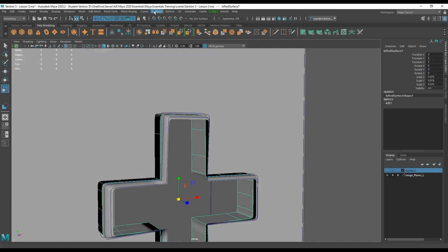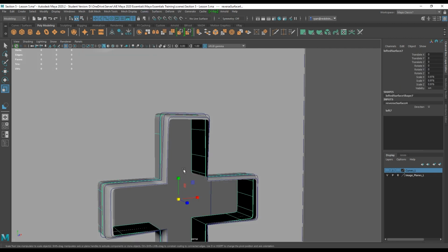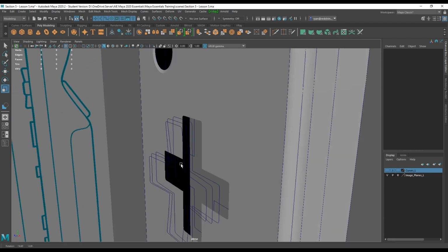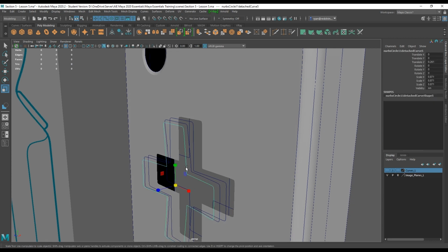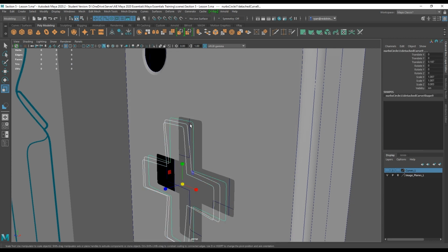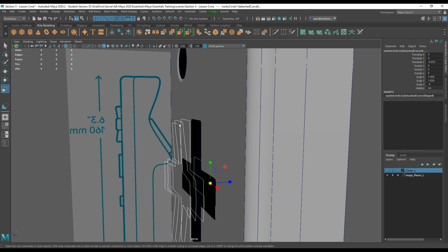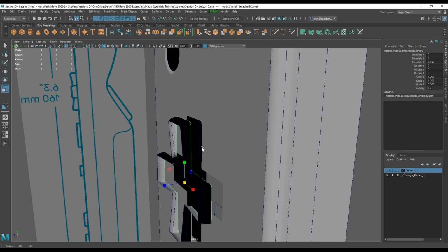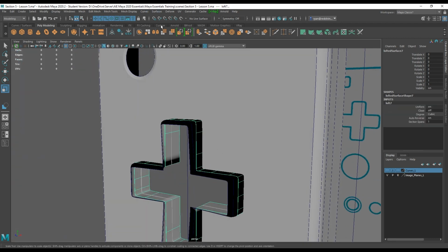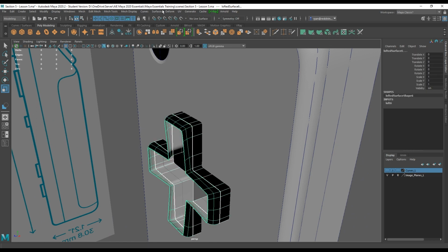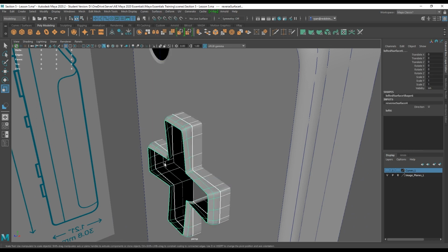This guy, I would need to go surfaces, reverse direction. I'm going to delete these surfaces. Do that again because the curves were kind of going beyond the surface. Again, down. For interest's sake, I want to see what happens if I have this guy included in the loft. For some arbitrary reason, it collapses in on itself. Okay, let's go back to our way of the future. Surfaces, loft, outer curve, and that inner curve. And we can go surface loft, get that straight line that we're looking for. Then of course, last but not least, grab the surfaces and reverse their direction.